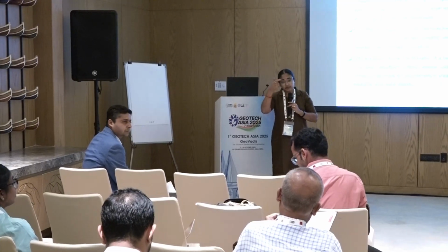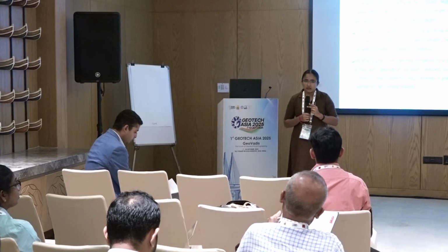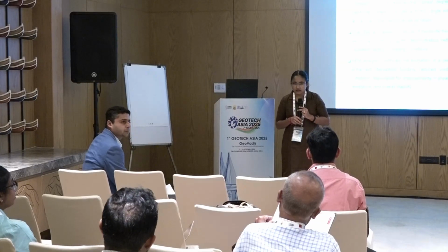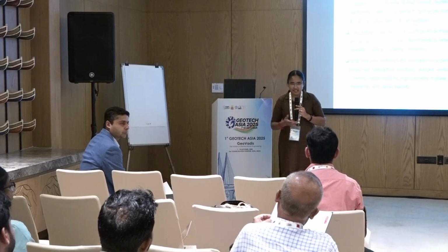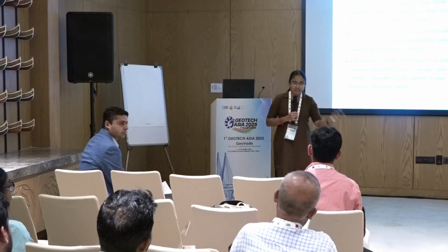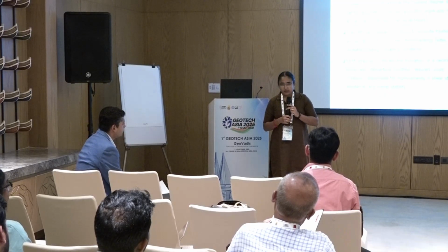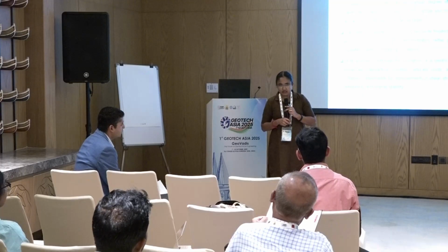Whether you do it with the XG or with bentonite, if it is not satisfying the wetting drying cycles, what then? Bentonite is satisfying. Xanthan gum was not satisfying, it crumbled. Addition of bentonite was satisfying the wetting drying cycles.